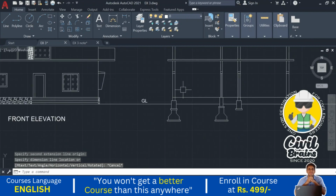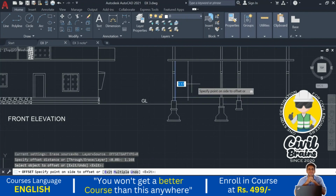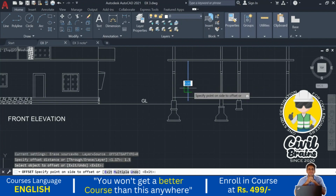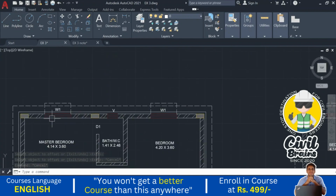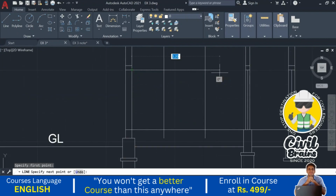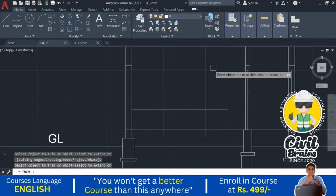I just give the offset command, offset 1.168, press enter, from here, and offset 1.5, and here it is. Okay, from the lintel level, what is the sill level of W1, that is 1.4, offset 1.4 from here, press enter.